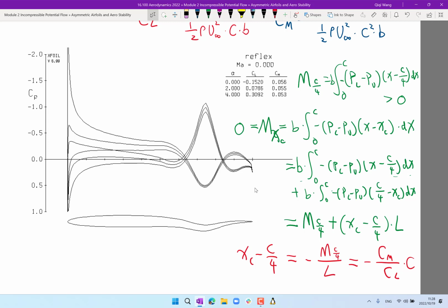Here, the moment coefficient is about an order of magnitude larger than the error of the thin airfoil theory, so it's okay. But if the moment coefficient is 0.00 something, then that's a place where the thin airfoil theory is no longer that trustworthy, and it's better to actually calculate the numbers and make decisions according to the numbers.